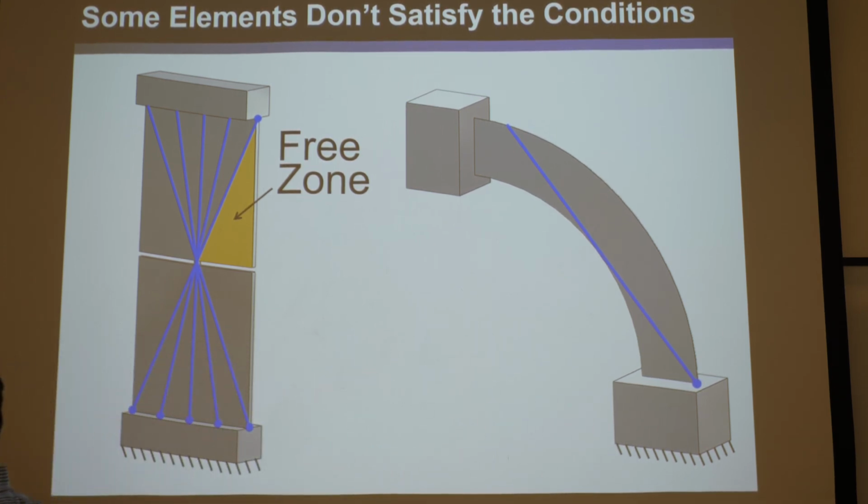And so if an element doesn't satisfy one or both of the parallel element conditions, it is not a parallel element, and do not analyze or design it using the rules I've taught you in this lecture. It is at your peril. You might get a freedom space that's correct, luckily, but there are many that will give you the wrong freedom space. I will be teaching you how to analyze serial or hybrid elements in a later lecture. These are both serial, by the way, as that says. Okay, so that's that section.